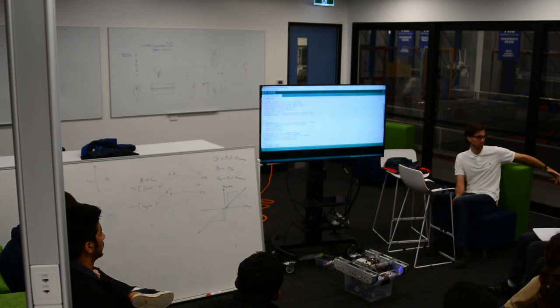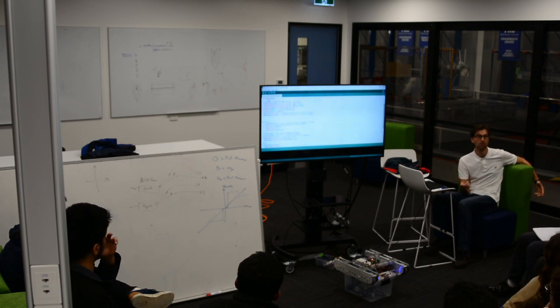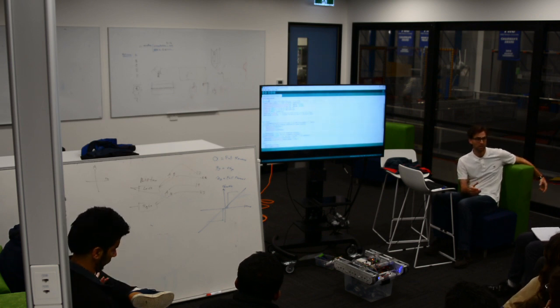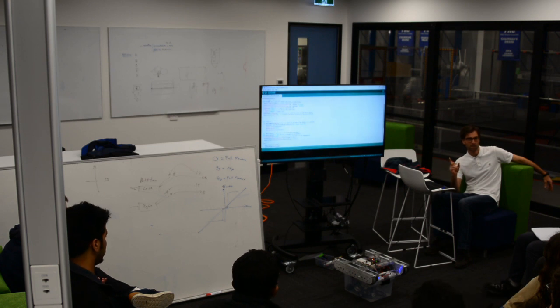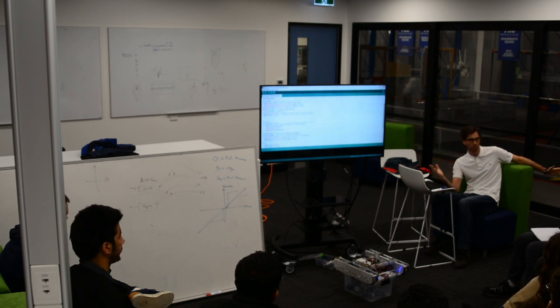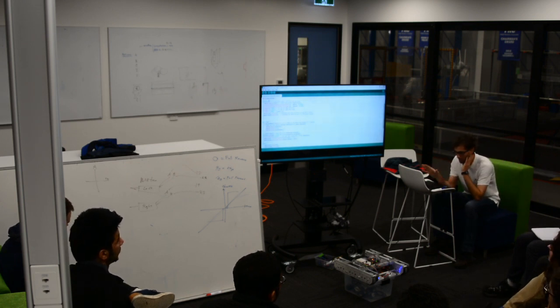Okay. Now, this took me a little while to come to because you run into issues of float math versus int math. So now we're multiplying non-integer numbers and we're using non-integers. Now the Arduinos, many of you guys are software and computer type folks, right? And the Arduinos are simple, they're not MATLAB, right? And so if you take an integer like 5 and you multiply it by a float, or divide it by 6, you're going to get some weird numbers, right? And you're not going to get what you want. So I've done a bunch of things to fix this up.